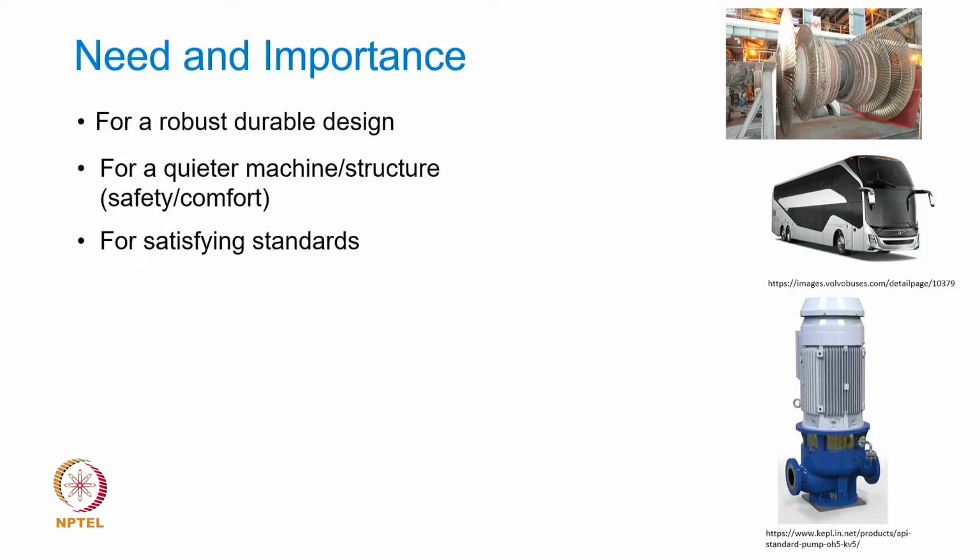Then many times the machines or equipment are also designed to satisfy standards. For example, for a pump that you see here in this picture, it is not enough to simply design it for a given flow rate and given pressure requirements, but it is also designed right at the design stage to satisfy some standards. For example, pumps are typically designed to satisfy standards such as the American Petroleum Institute standards, API standards, and in that sense the designers are not only supposed to understand the basic things, but also vibration based design aspects, and therefore if you want to be a designer, you have to have an in-depth understanding of vibration as a phenomenon.